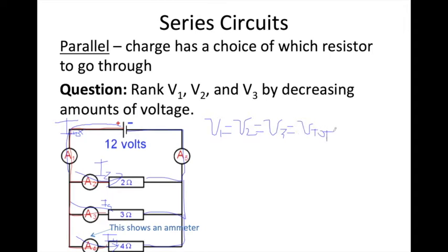Now the piece that ties this all together is, how do the currents relate? How does I total relate to I2, I3, and I4? Well, take a look at one of these branching points right here. I hope I can convince you that, because current in equals current out, the total current has to equal I1 plus I2 plus I3. The currents have to add together. You can see that on either side. And if you don't believe me, you can smear all these points together into a single branching point for everybody. It's a little misleading in this diagram.